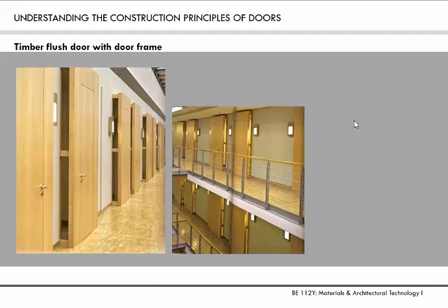And a timber flush door, you can see that there is no architrave. Remember we studied about architrave. It's flush with this frame here, so you have a flat finish. Really, it depends. If you want a clean finish, you need to learn how to detail this, so that you can draw the drawings and give them to the contractor. Similar for the louvered doors and whatever forms you want. You need to understand the basic construction principles of the door frame, your jamb, your rebates, and your door leaf before you can know how to draw such a detail.